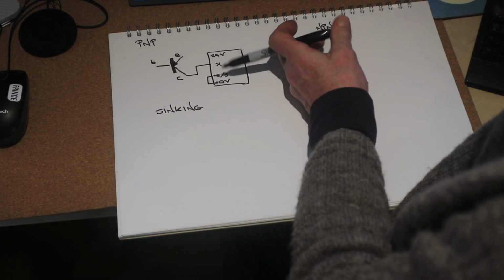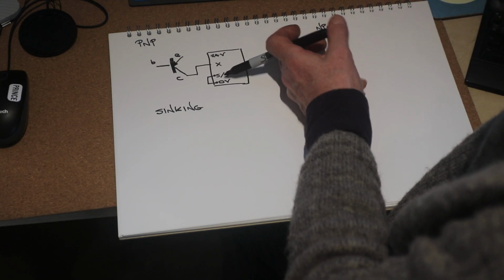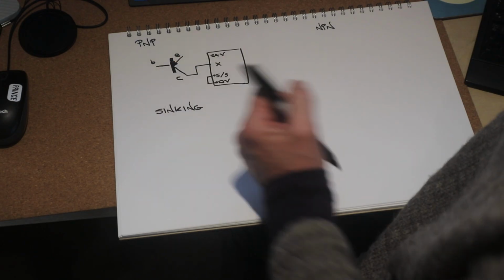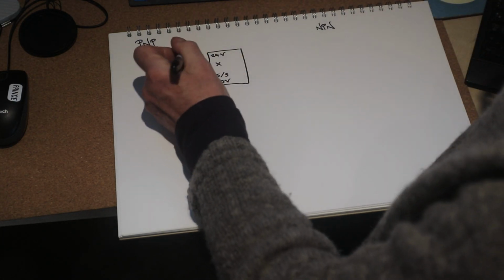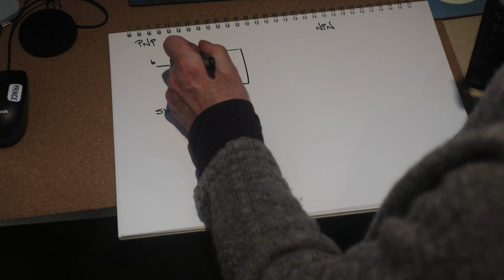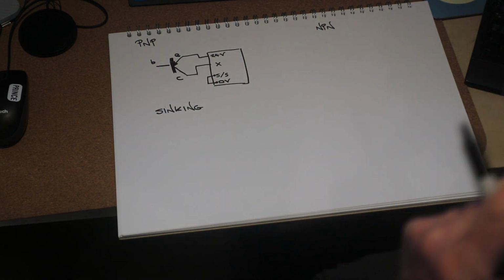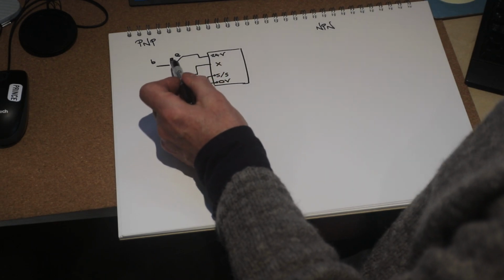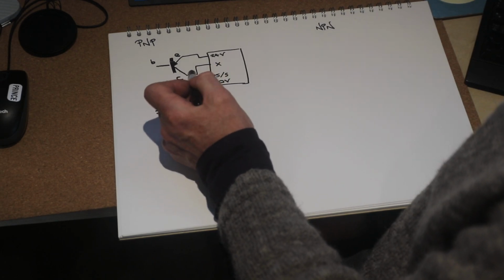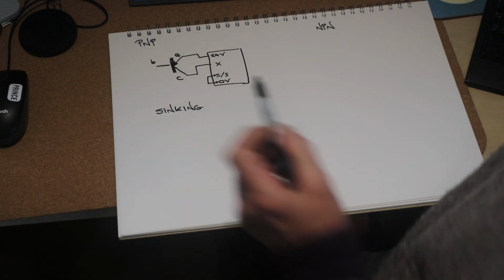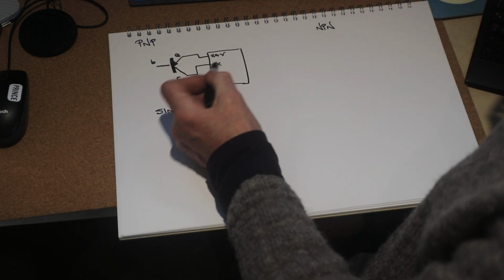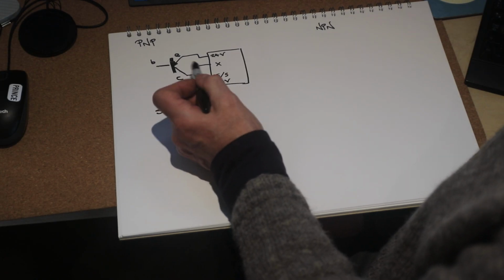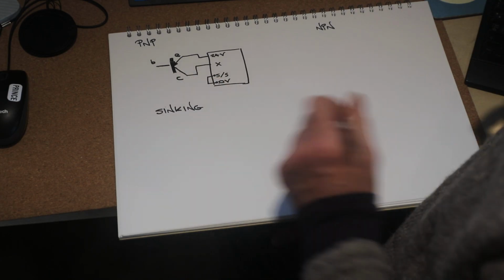Because we've connected it to 0 volts, it's going to be sinking. You've got to imagine this is a big electrical hole into which we can pour electricity. The other side is going to be connected to 24 volts. Yeah? So it's going to take power from here and drop it into the input. So the input's now connected to 0 volts via sinking and sourcing, and so this will work as a whole.